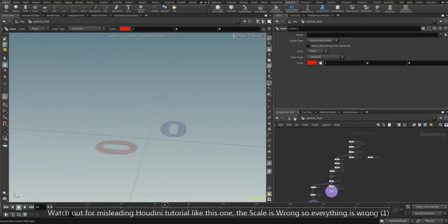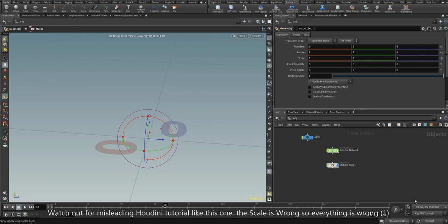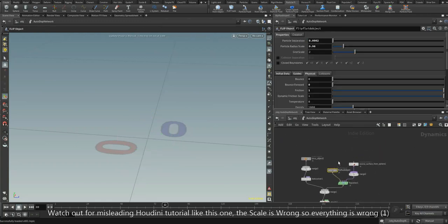Okay, so this is my flip simulation. Houdini will create the flip simulation automatically for you. So just go inside, right? This is the setting I'm using, so you can follow my setting. Give a very small particle separation. In this version of Houdini, I found that even on Windows, the performance has increased. It's awesome, very good, and very efficient in memory.